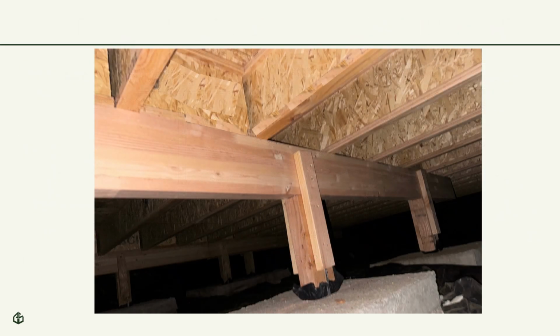In this picture, we can see what blocking of joists may look like if required due to alignment with an interior brace wall panel. Note that similar to horizontal blocking in the brace wall panels, the blocking we just discussed in the IRC figures are only required where there is an interior brace wall panel, but there may be blocking required for other reasons, such as at bearing supports of the joists.